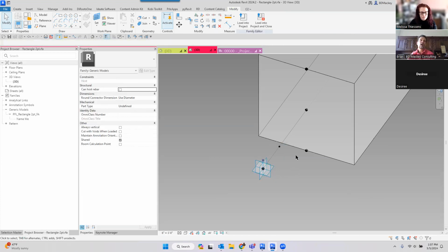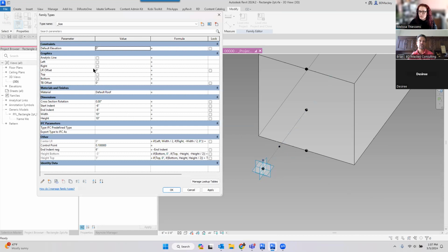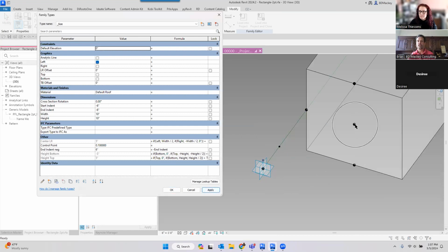So I come through here, I do points on points on points. If you look at this, I then went through and started adding things like, I wanted to offset this to the left. So when I do that, this point here was associated to that point. That point's associated to this point. These 2 points are associated to that point. So again, no parameters on here, but I'm just using the offset values of all of those.